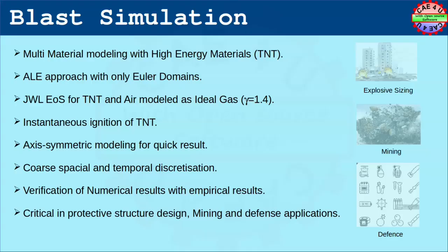To effect explosion, the explosive has to be detonated or ignited. So in this case, an instantaneous ignition model is used. Because of high pressure gradients, blast simulation will typically require high grid and time step resolutions. However, to reduce computational cost and fit within the available computational resources, 2D axisymmetric modeling was adopted, which also harnesses the geometrical and response symmetry in this problem.